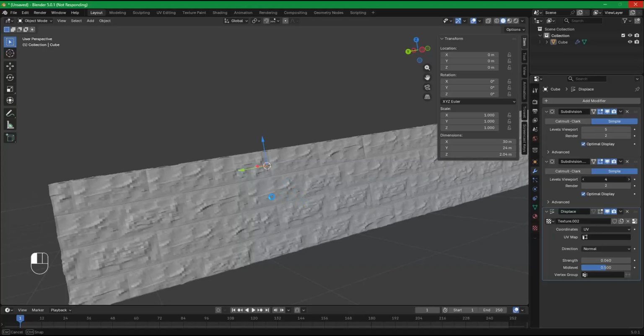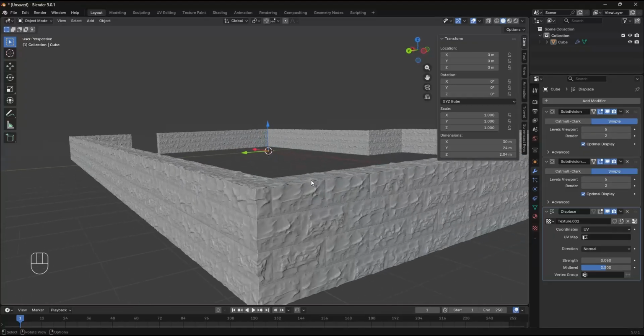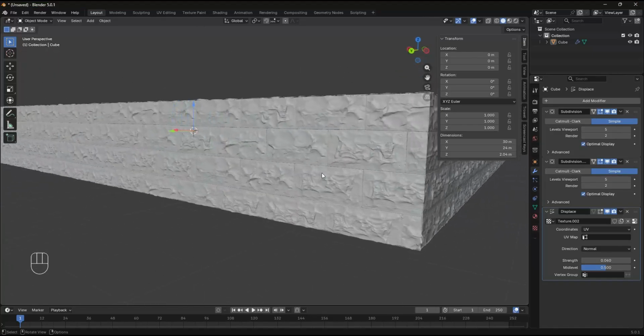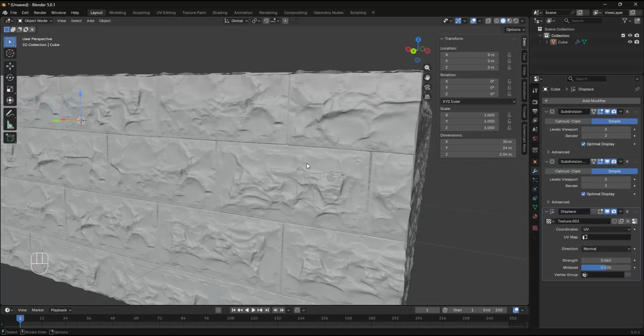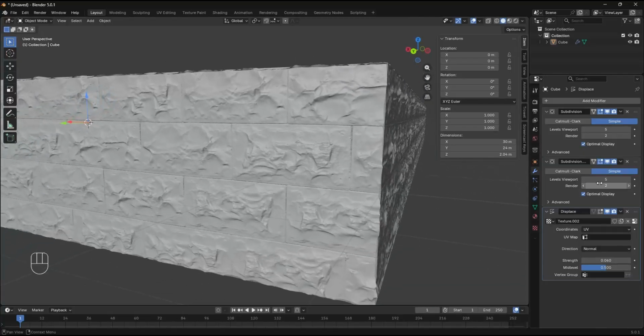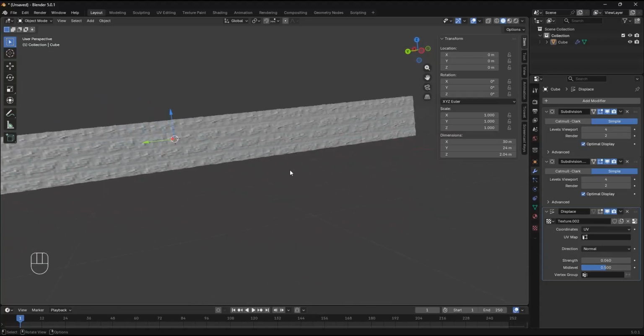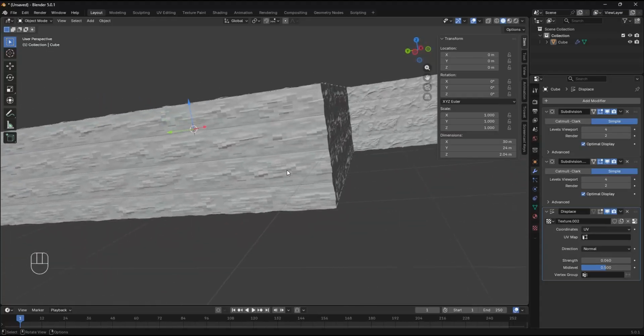And you can see that the 5 here is really slowing down the computer a lot. So I did take these both up to a 5, and it really does get some super resolution out of it. But a little bit concerned it's going to really probably take too much memory, especially when you make the print file. I would recommend probably just taking these both back down to like a 4, and then creating the print file at that point. Maybe it doesn't look as good on the screen, but I'm going to guess this should probably print okay.